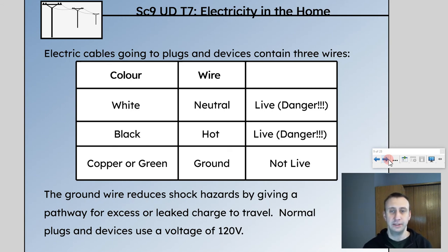I'm going to say right away: never, ever, and I mean at this age, never, ever play with your outlets, period. But as you get older and you're dealing with different stuff in your house, and maybe you have to replace something like an outlet or a switch, turn off the breaker in that area. Check the outlet first with a device like a lamp to make sure that it's not connected, and double and triple check before you touch the wires.